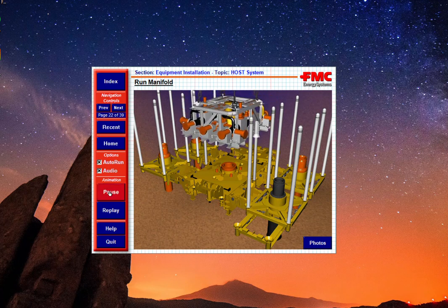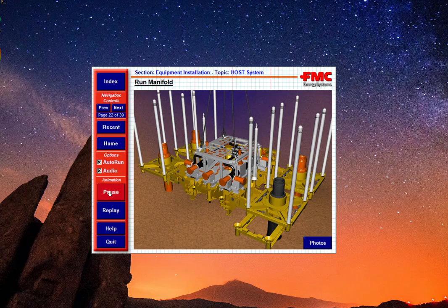Manifold is made up of a 10-inch production and 6-inch gas lift, which contains 6 by 2-inch branch lines rated at 4,200 psi working pressure. The manifold assembly is lowered into position. Once landed, the manifold assembly is inspected by the ROV to assure proper positioning and alignment. The ROV releases the installation slings in preparation for the installation of the pig loop module.